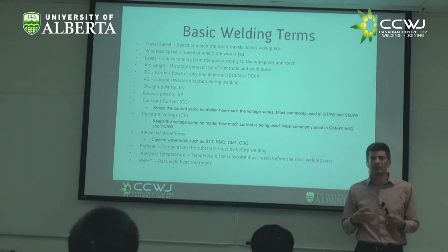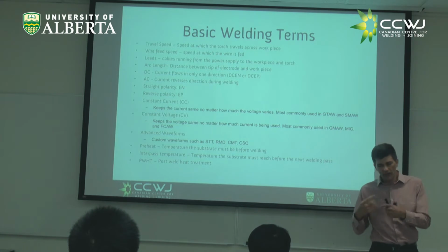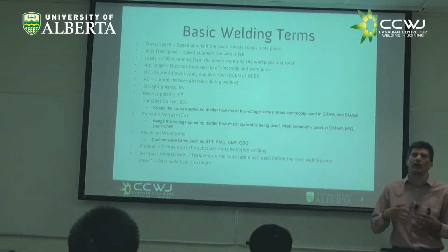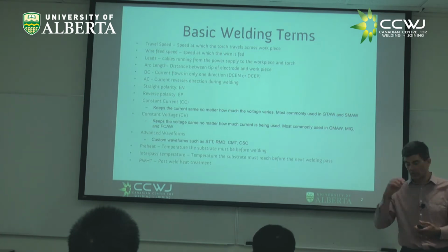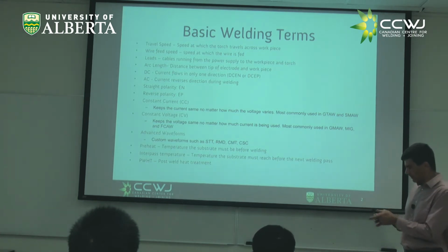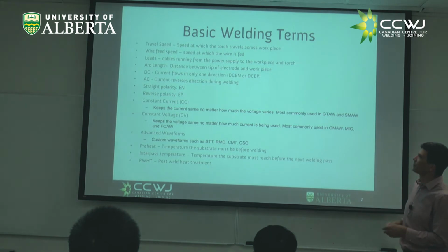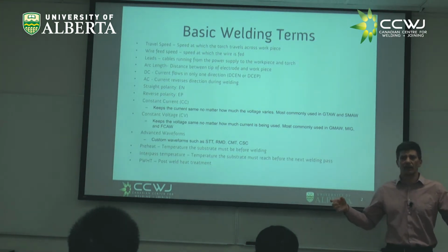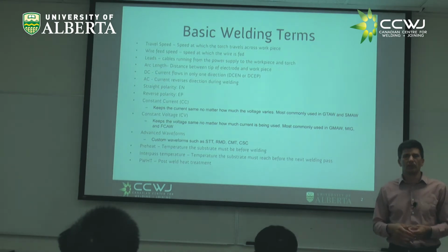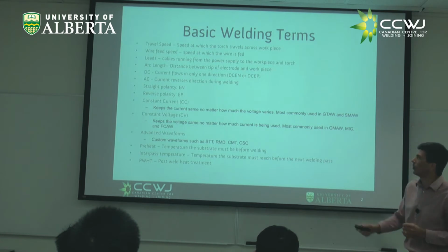Also, in some welding processes, you have a wire. You start to unspool the wire, you melt the wire, right? And you'll know everything about it, and you're going to see them in action. So the wire comes at a velocity too, right? That is what is called the wire feed speed, right? Then in electric welding, you have two big cables because the voltages are relatively low, but the currents are high, right? And those big cables are called the leads, right?